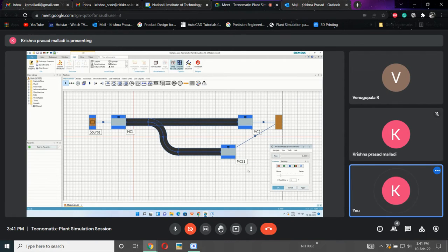There is no need of pressing 2D. Once we are done with the manipulations, see there are arrows here still, which means it is still in editing mode only. So we need to disable that one. For doing that, either you press M directly, so that everything will be enabled, and again you press this one, so everything will be disabled. M, M, right?